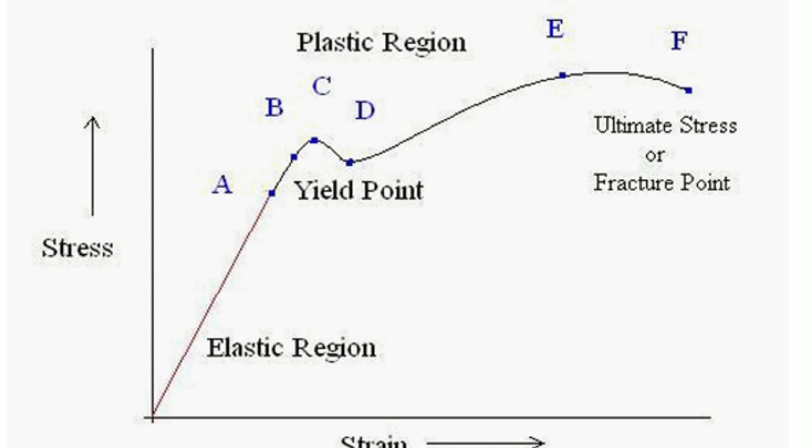Whenever we increase the load, it shows like this, and after E, when we increase the load again, what happens? It will come out like E to F. So what is E to F? In this portion, the load is falling off from the maximum and fracture takes place at F. So F is termed the fracture or breaking point, and the corresponding stress is called the breaking stress. Now, if we increase load from point E again, then the fracture will happen, and this point is called F, the fracture stress or breaking stress.